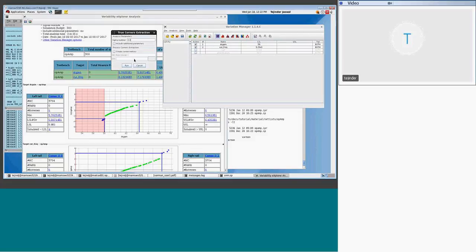So you can just set the Monte Carlo. You do 100,000 Monte Carlo and you extract the min max, where with only a few hundred you can do it. You include the VT, and the tool will generate the netlist. So for corners, the netlist that you can run, or run around Monte Carlo data. Customers are extracting the true corners, and once they have these corners, they run local Monte Carlo around them to check.